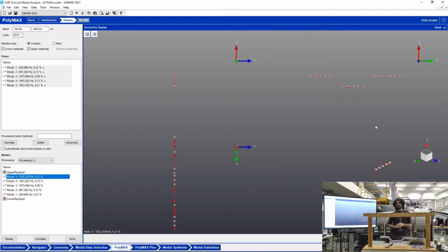That is the case because the natural frequencies are associated to the mode shapes. So the lowest natural frequencies correspond to the simplest mode shapes. As you go up in frequency, the mode shapes become more and more complex. Complex, not mathematically complex but geometrically complex, because these are all complex numbers. Anyway.